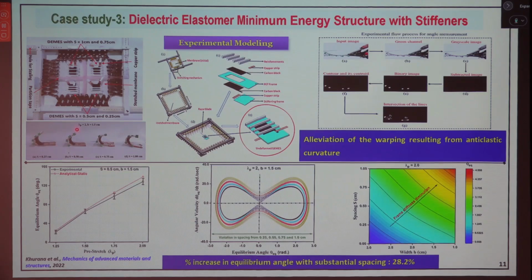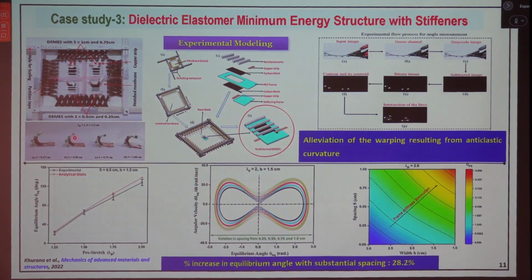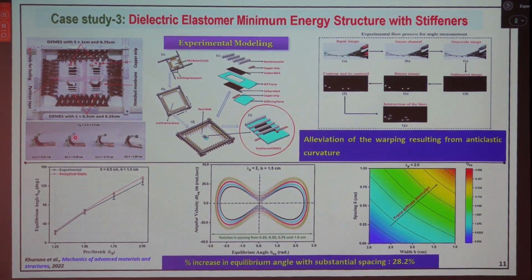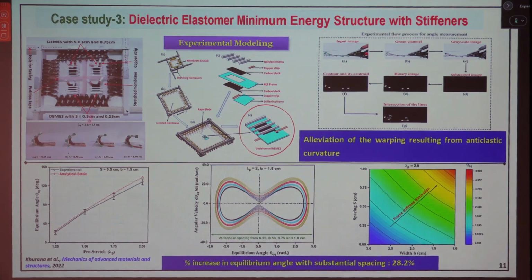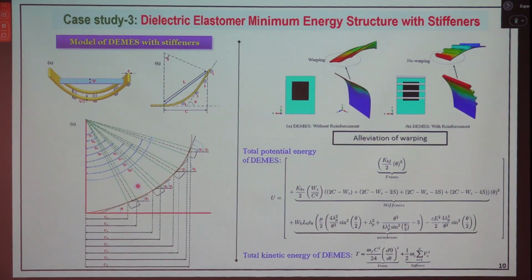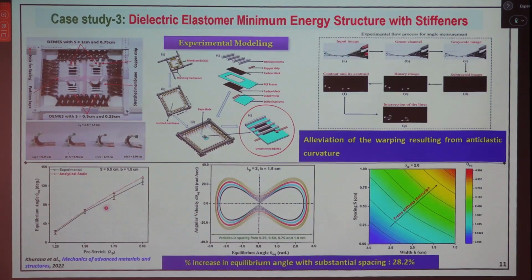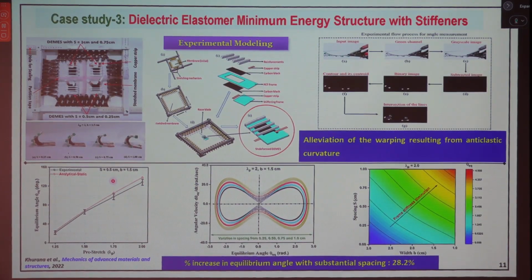In the second case, we apply the electrical voltage. When we apply the electrical voltage, I will show you, it will actuate like this, okay. As a result, we have the experimental result here, and a very complicated mathematical model. After solving, some source of discrepancy still remains. When we carry out an experiment, we have to carry it out multiple times, because initially we are putting the carbon grease by hand. If I replicate that two or three times, every time I will get some variation.